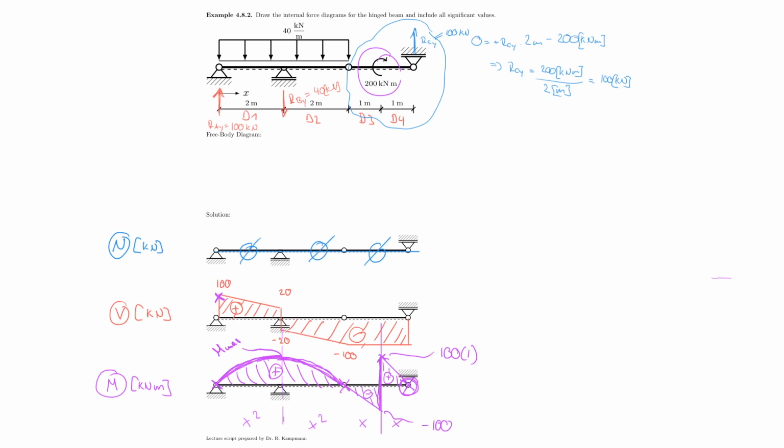And so you see, once again, the moment diagram is no different than before, except that your moment has to pass through 0, of course, where your hinge is situated, and nothing else goes through 0. In this problem, we also added this nice little feature of the concentrated moment to make us aware of the fact that it has an effect on the moment diagram, but nothing on the shear force diagram. And I think this concludes the problem, and we solved it completely.